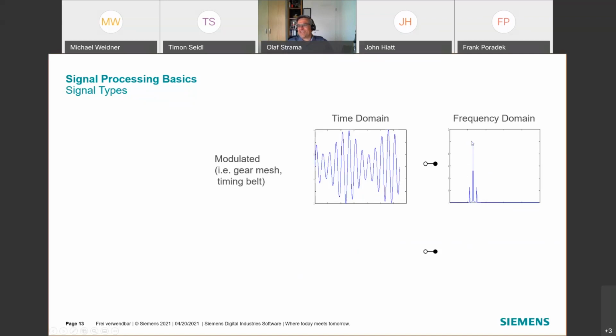That means you do not only see one line of the carrier frequency, you see twice the carrier frequency, 3 times, 4 times, and so on. And the frequency that is modulated on this carrier is shown as sideband lines. This is a kind of FFT rule. What we are doing here is an FFT spectrum. And a mathematical rule is, if we do a multiplication in one domain, in our case the time domain, then this leads to a convolution in the frequency domain.